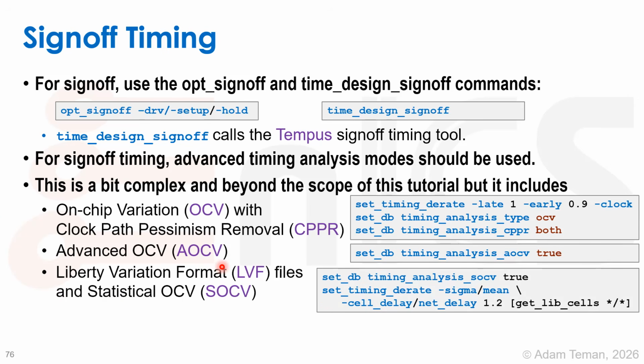Okay, but that was also found to be an overkill and not good enough, and they want to remove more pessimism, and that is where statistical timing analysis came up. So first, Cadence came out with this SOCV or statistical OCV, and Synopsys came out with POCV, parametric OCV. There is no current standard as far as I understand, but at some point the Liberty Foundation or whoever makes these Liberty files, lib files, came up with a new format called LVF that puts some of this statistical aware type of timing information inside one file.